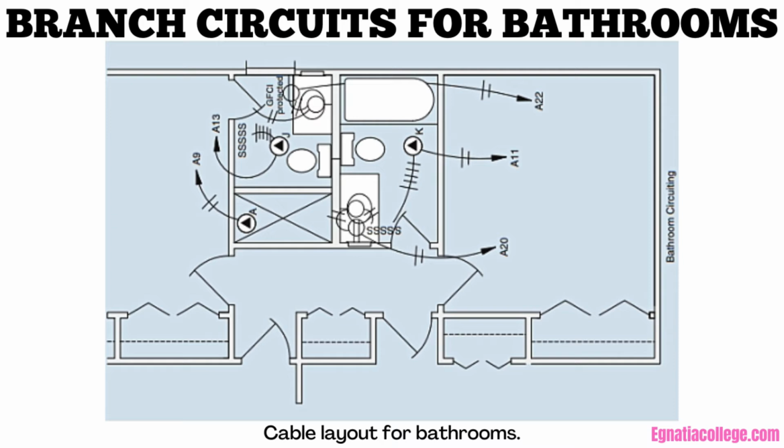Because the receptacles in the main bathroom and in the ensuite bath are likely to be used in the morning at the same time by people using hair dryers that draw as much as a toaster or kettle, 1200 W, we have put the receptacles on their own circuit with the vanity lights. This is not a CEC requirement.